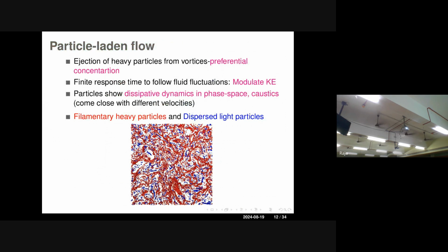Whenever there is a swirling motion, if they have inertia, they will be thrown out by centrifugal forces. Wherever there is a vortex, up to the integral scale of the vortex structure, particles will be expelled. So you will have clustering phenomena happening in these turbulent structures. And there are always strain zones where they will be pulled away. Based on volume fractions, they change the topological nature of particles in turbulence. That means your ensemble averages, or the macroscopic nature of this entire drag, completely changes.